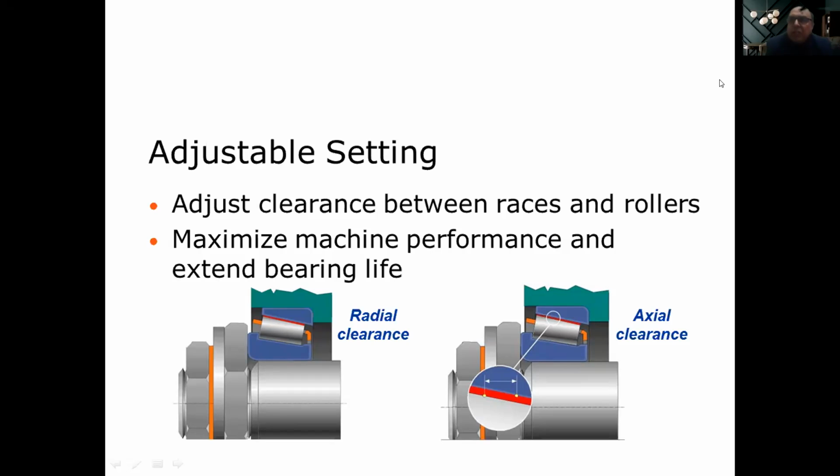I think the play or backlash you are talking about in bearing, we call it a clearance. I mentioned this before, but I will repeat that in a typical high-speed application, you will require some play. But in an application where you require a lot of stiffness and rigidity, like a machine tool, there you actually are preloading.